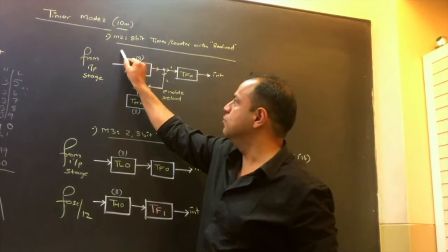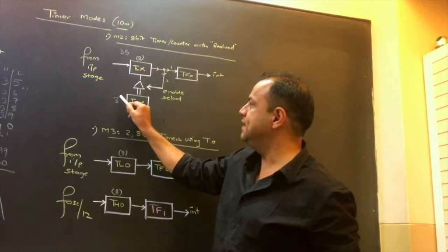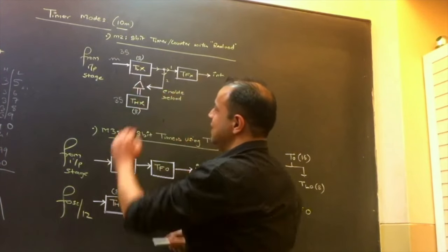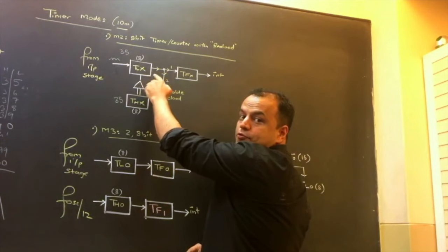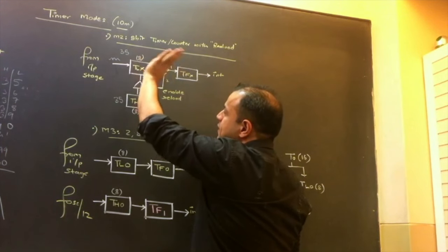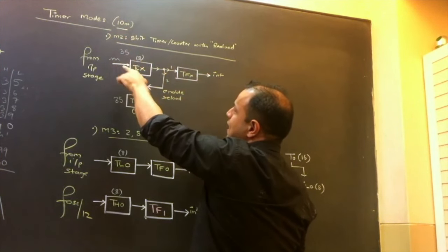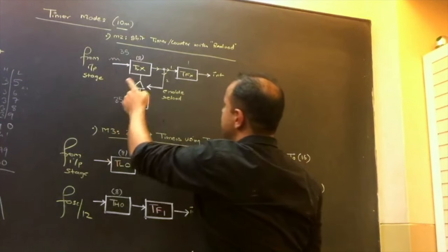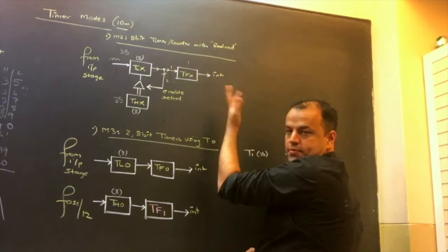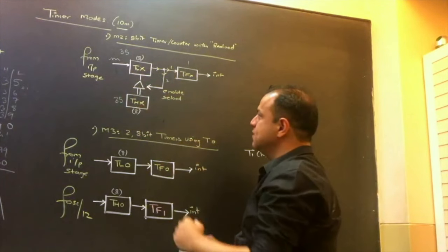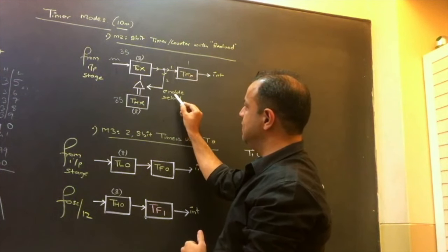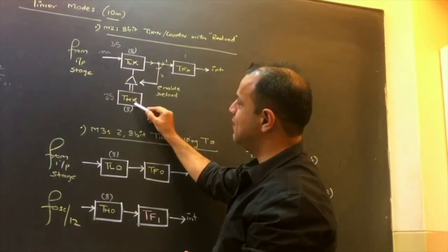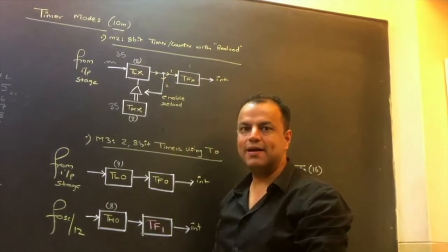We put 35 in both TLX and THX. On every clock pulse, TLX will increment. So this is the one used for counting. TLX will increment. Eventually it will overflow. As you can see, when it overflows, 2 things will happen. First of all, it will make the overflow flag 1 and send an interrupt, because this count is over. At the same time, it will enable this buffer, which will enable a reload. Enable a reload means the value of THX will now be loaded back into TLX.